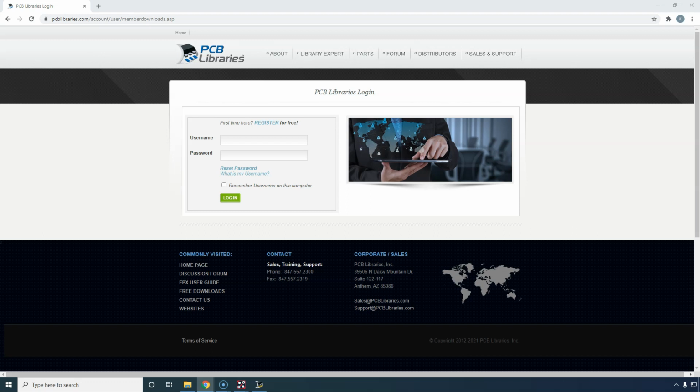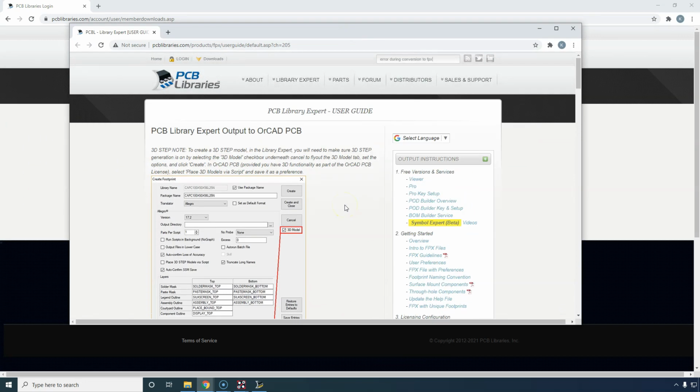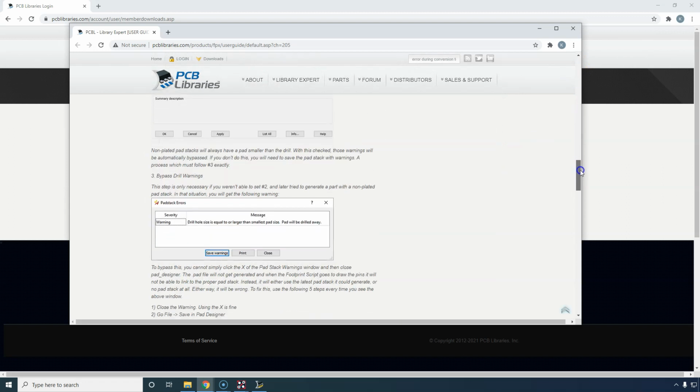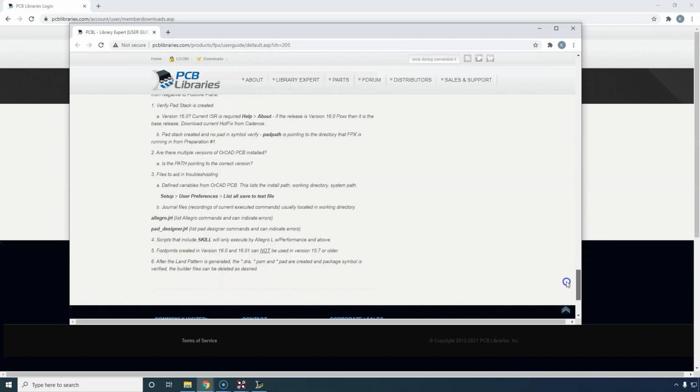But here's a tool that generates the names for the footprints for you, generates the details for the footprints and the measurements to the IPC standards, and also based on updated information since IPC 7351B. This is where you want the most updated stuff.